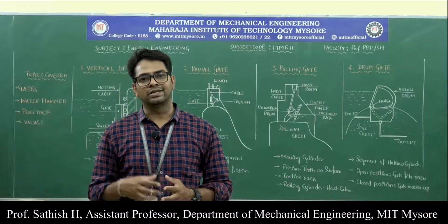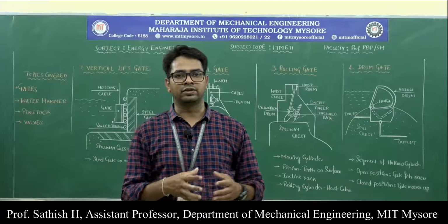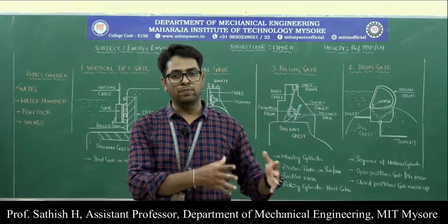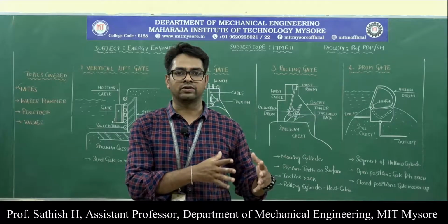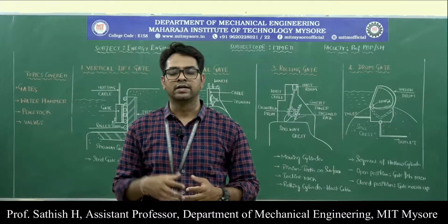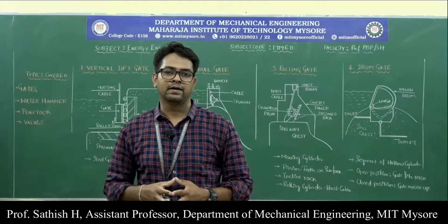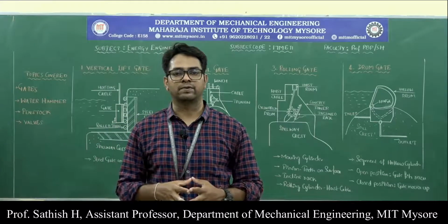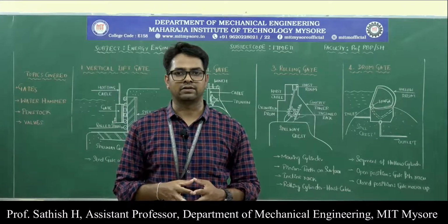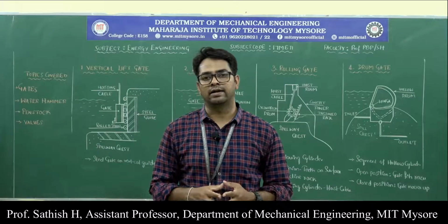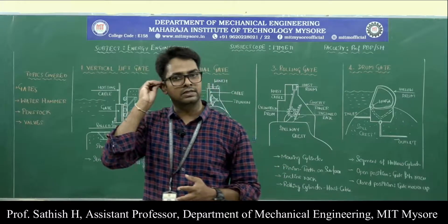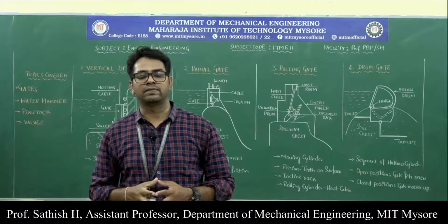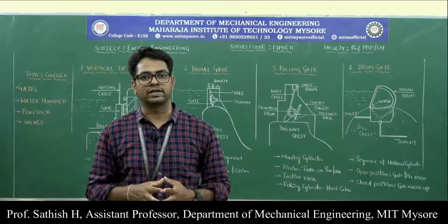That will also result in fluctuations of the pressure. These fluctuations of pressure are due to the sudden opening and closing of the valves that transfer the water through the penstock to the turbine or the powerhouse. That fluctuation of pressure is called the water hammer effect. While designing a penstock, you need to consider what pressures might occur due to these water hammer effects.